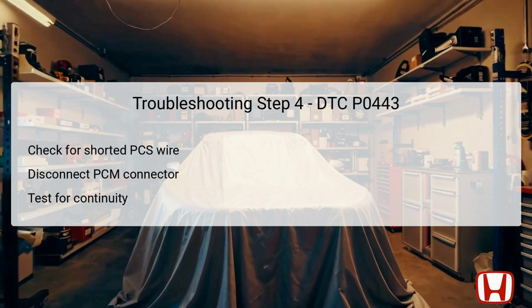Then, proceed to disconnect the connector B51P from the powertrain control module, PCM. With these connections undone, measure the continuity between the 2 specified test points. The first test point is the number 1 terminal of the EVAP Canister Purge valve 2P connector, while the second test point is the designated body ground. Ensure that the vehicle is in the off position during this testing phase.